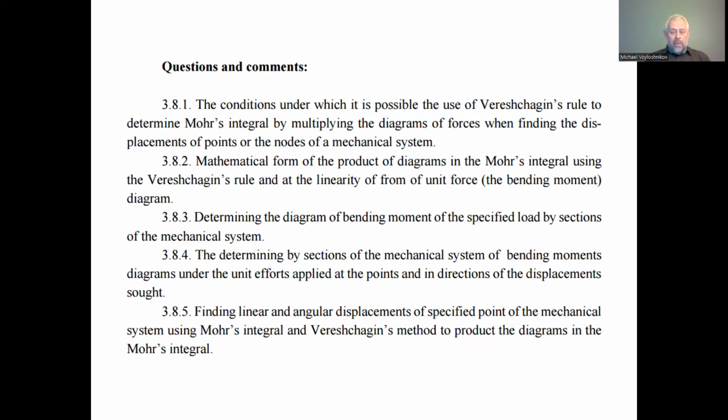In this case, instead of direct finding of the integral itself, we can find the product of the area of the curvilinear, maybe parabolic, diagram of any shape, and we have to find the location of the center point of the area of the curvilinear diagram of the external force.